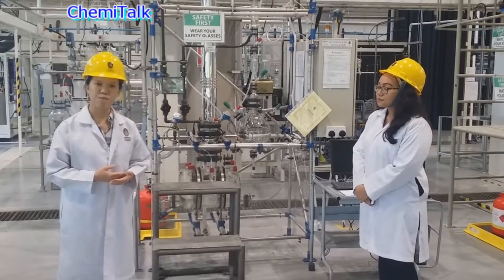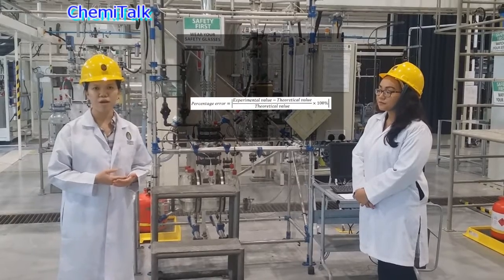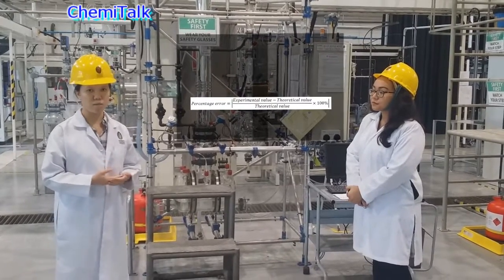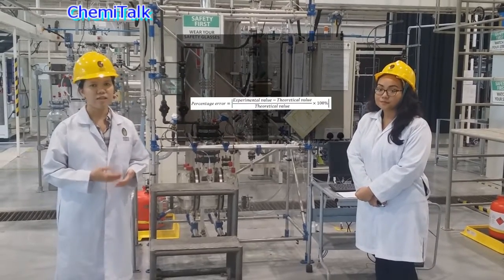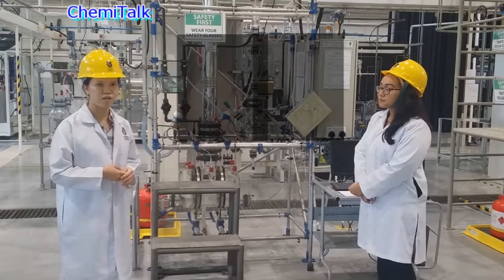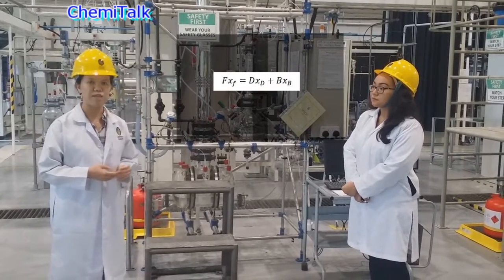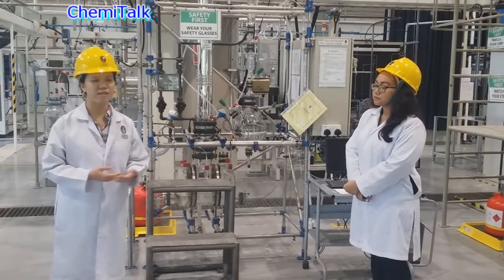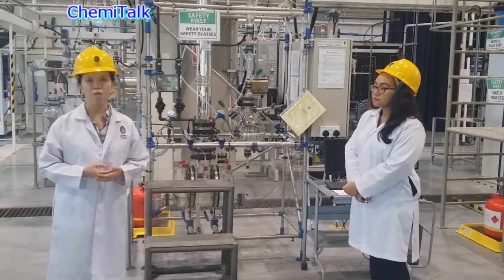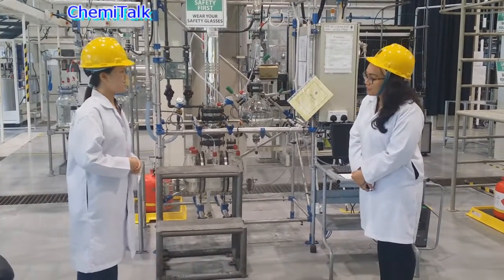Last but not least, the percentage error is being calculated. The experimental value is the initial reboiler composition, which is 0.647, whereas the theoretical value is calculated from the equation F x_F = D x_D + B x_B. As a result, the percentage error in this experiment is 40.43%. Thank you, Ms. Lee Ziling, for explaining the details of the whole experiment. You're welcome.